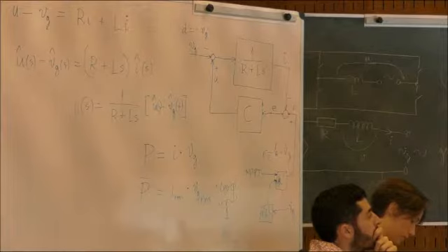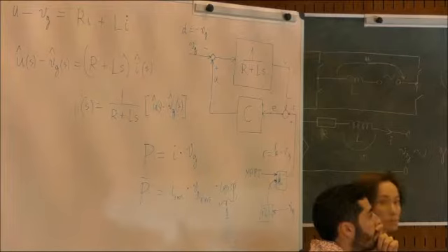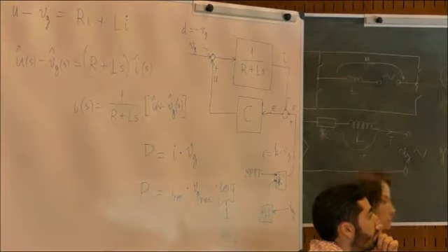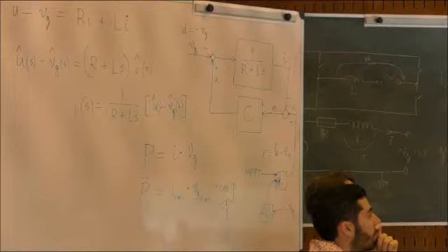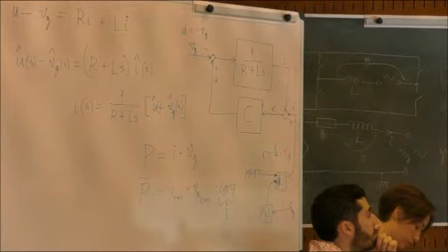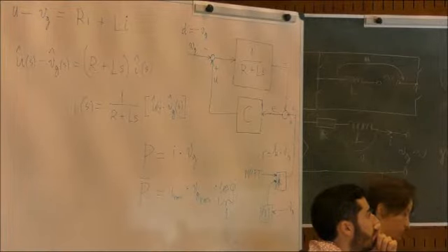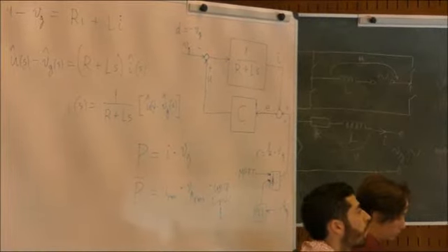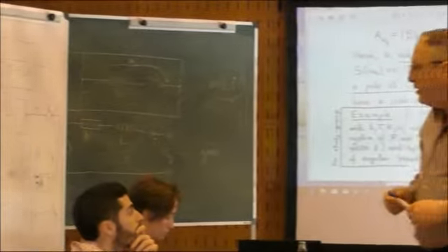Let's say something is rotating, and it has some protruding part, and each time it comes to a certain part, it has a friction, and then the torque is big, and then it moves away from this contact, and then the torque is small, and then it comes back, and again it touches here, and the torque is big, and then it moves away, and the torque is small. This is actually very typical in drilling.